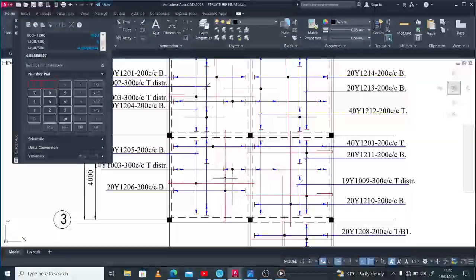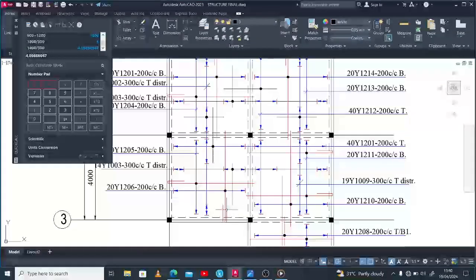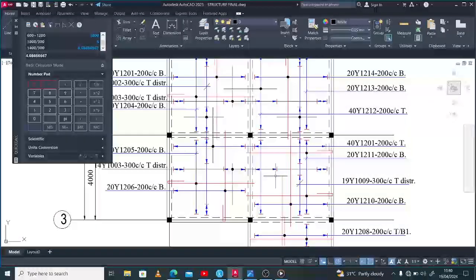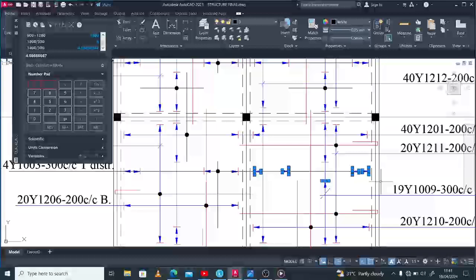So this also works from here to here. All right, then to this place, and then covering this place. Okay, so in this case there is something unique. If you discover that this top reinforcement ends here and the cantilever reinforcement here ends here, so it means that your top reinforcement might not work or should not span all through this place just this way because of this arrangement. So you may need to just take this off